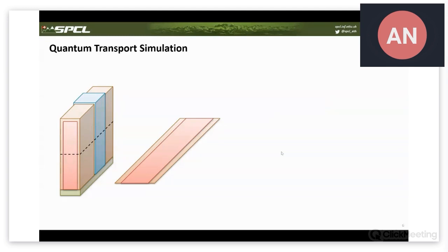If we look again at the channel of the transistor, we have the electrons. Each electron has some energy, but it also has another quality that we call momentum. The momentum is basically an angle, and it's more or less the direction that the electron has while traversing the channel. Now, we can start with a simplified model where we make the assumption that the electrons do not interact with their surroundings. So when the transistor is on, they basically cross the channel, and they keep the same energy and momentum, nothing changes. This is what we call the ballistic transport, and obviously it's not very accurate.